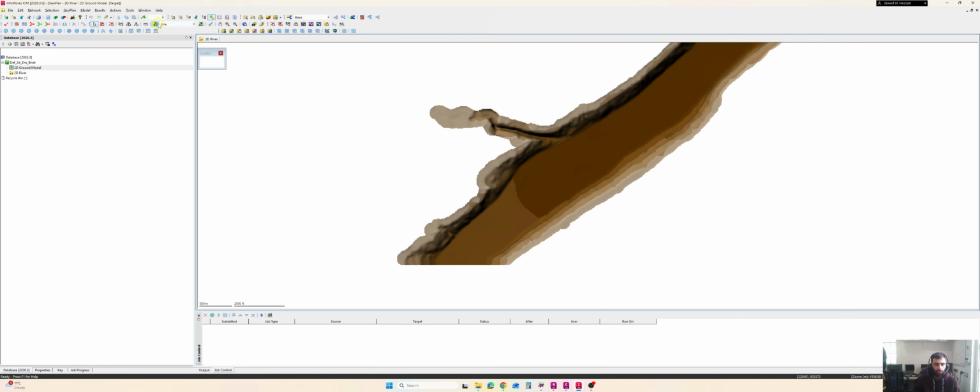For the 2D zone you can see this area. You drag and drop the polygon. So we need a polygon and select this one, new object, and start digitizing nearest point. So this way we can design our 2D zone.